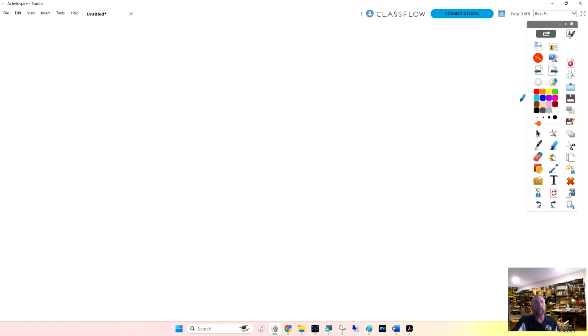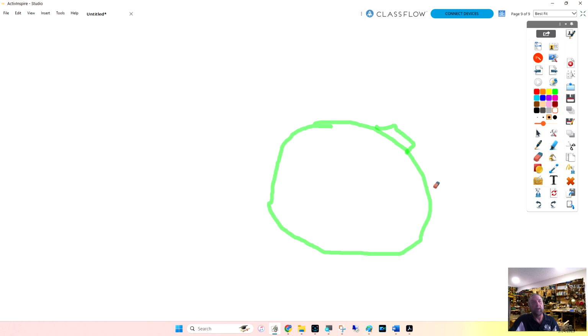So let's take a look at something here. I know I had a thing with shapes. I could have drawn a circle nice, but I'm not going to look for it now, time-wise. So you got a circular cam. And on that cam, you may have portions that are raised up, and you may also have portions that are cut out. Now, you have those 3 pins on the timer. The center one is the one that rides on the timer cam.